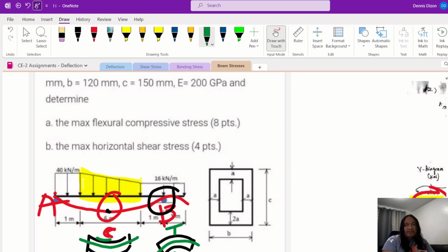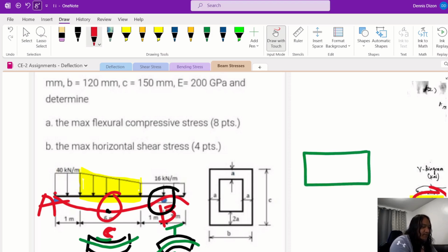The section is a single type of material. But if this is concrete, where in tension you rely on the reinforcing bars, that's why above a support, your main reinforcing bars would be at the top, at the support location, because this is where the tension is, above the neutral axis.